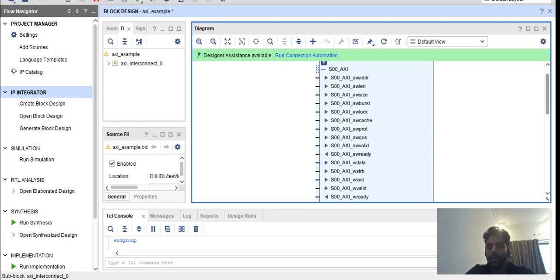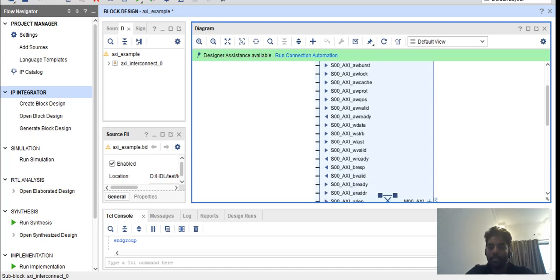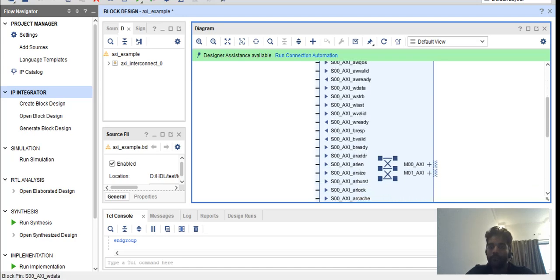Similarly, if you look into the naming convention for the data, it's just data, write data, and strobe, valid and ready, just 5 signals here. Just ensure this handshaking is happening properly and send the data accordingly. So you have to wait for the ready from the slave. If your slave is active, you just have to monitor this ready signal. Whenever the ready is available, you can start sending your valid data. The address has been already issued, and the burst type has already been issued.